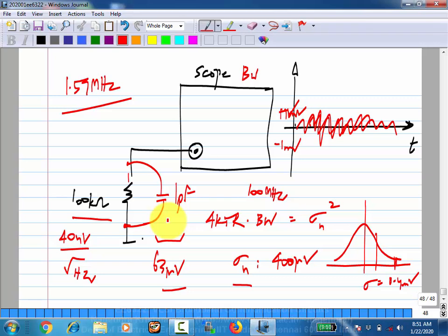So now we have hopefully a reasonable working knowledge of noise models. We went into some very basic concepts of random processes and so on, but essentially most of our calculations will involve applying the noise model and calculating the spectral density. But you do need to know what that spectral density relates to, right? Just like when you do frequency domain calculations, you need to know how it relates to the signals that we see in the lab in the time domain. Similarly here also you need to know. So that's why we went into this concept of autocorrelation, etc. So the size of the noise, so to speak, is specified by the variance, and that you can calculate from the spectral density.